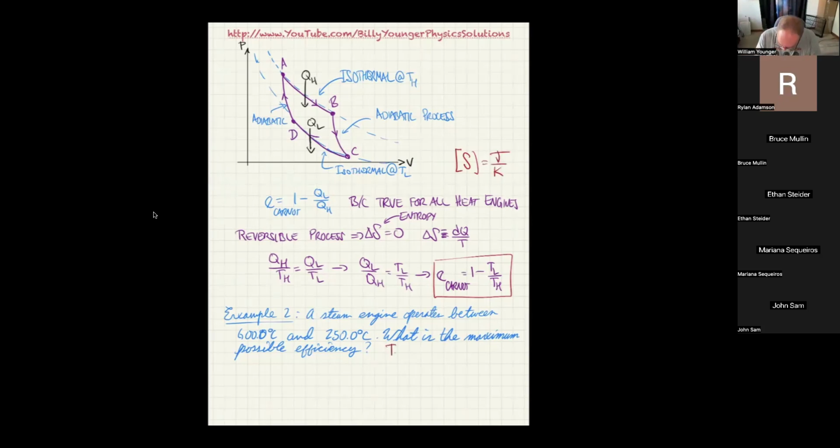So I'm going to say TH is equal to 600 plus 273, that's 873.2 Kelvin. And T low is 273 plus 250, that'd be 620.2 Kelvin.